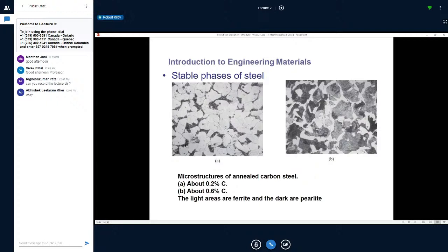Now, this picture is not the greatest. The dark areas, this is 0.2%, so 0.2% carbon. So it's not saturated yet. If this was polished better and it was a better picture, the dark areas would have those parallel lines, but it's not polished well enough and not magnified enough to show them as a series of straight lines starting to fill in the crystal. Remember, you need 0.8% to have these completely filled in with those lines of carbon.